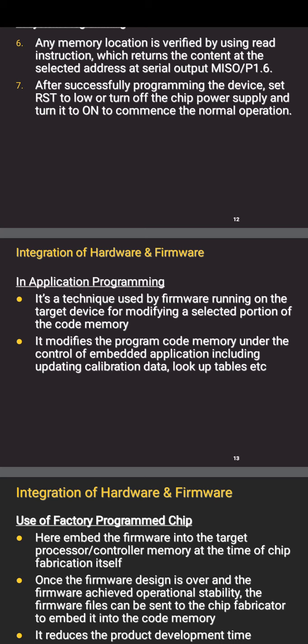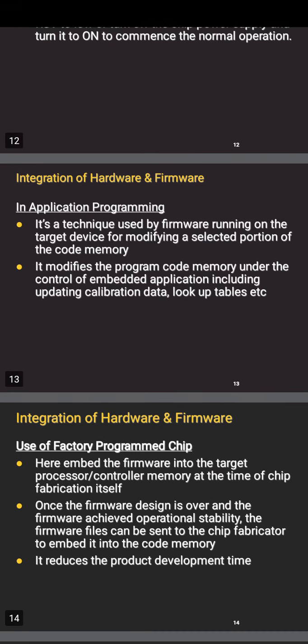It can only modify 1 kilobyte of boot memory, and this boot memory is provided either by the chip manufacturer or by the firmware designer. And this in-application programming cannot be modified by the user. Normally it can only be modified by the chip manufacturer or the firmware designer.